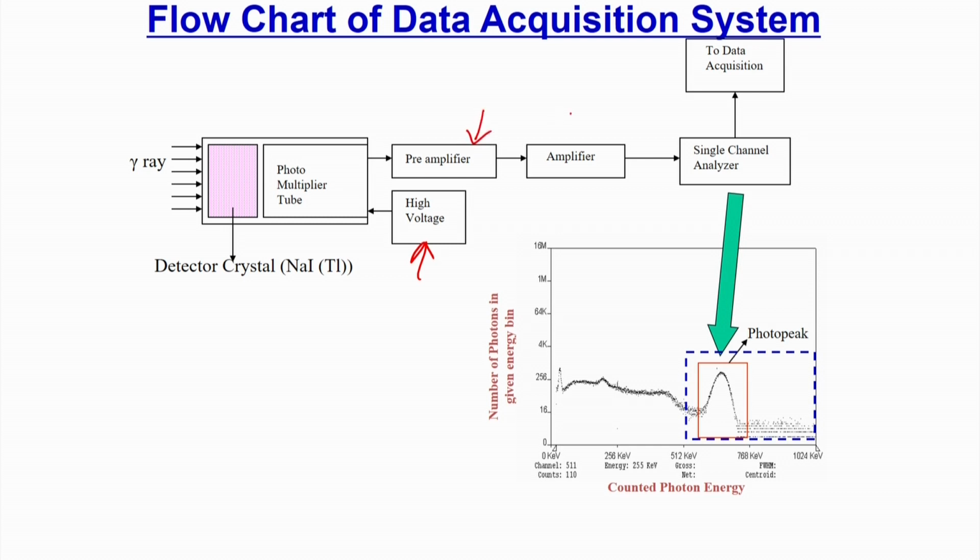We can have a pre-amplifier, and we can have an amplifier which will amplify the signal, so that I can see the signal and discriminate it from the noise. Okay. So, I will get that amplifier. Then we use a single channel analyzer or multi-channel analyzer. As I said, a single channel analyzer has a single channel which records or counts the number of photons incident on each detector. So, this is nothing but a counter, but it is also a single channel analyzer.